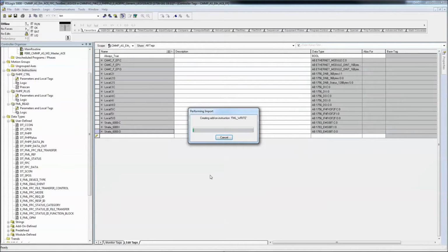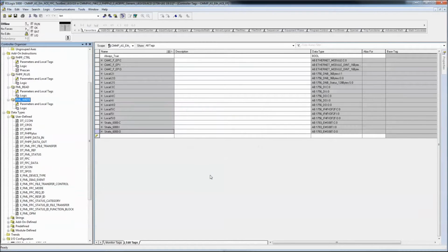If you're just doing basic control, this should be about all you need. You've got the control, which will act on the variety or the majority of the controllers that Festo offers. I think the motor DCI is excluded. The FML read and write map the real world data and configuration. This is the main control block, and the FHPP Plus is something that you would modify in the FCT project and configure what you have mapped to come across.